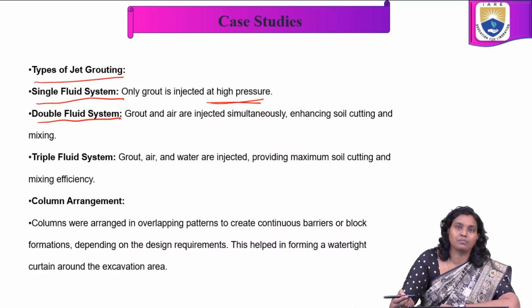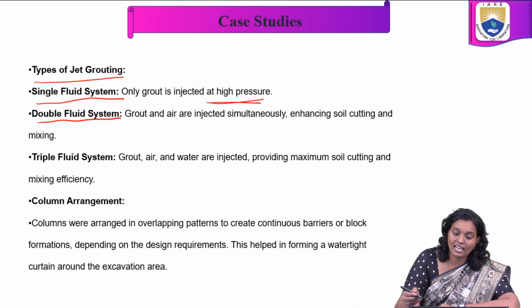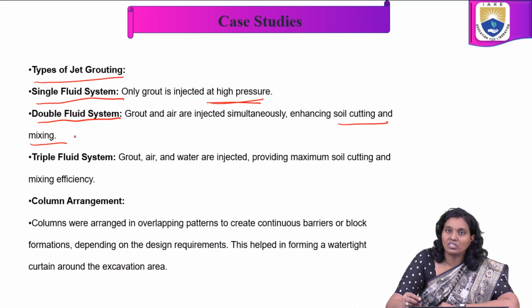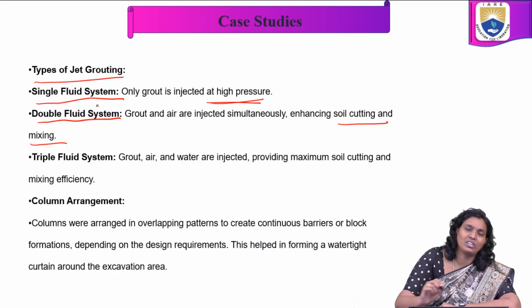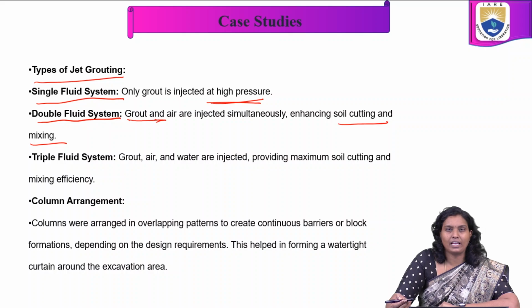Double fluid system: grout and air are injected simultaneously, enhancing the soil cutting and mixing. Whenever the project or the elements demand enhanced soil cutting and mixing, we choose the double fluid system, which is nothing but grout and air injected simultaneously.